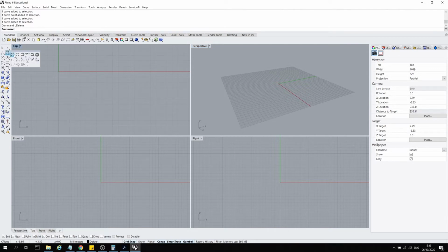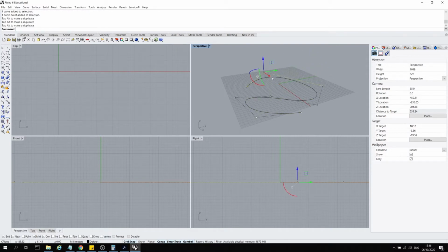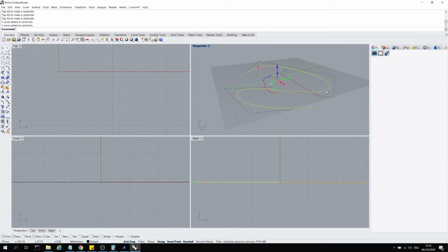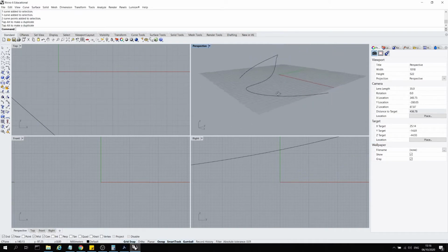We can also draw a curved line. This will allow us to draw perfectly curved lines through control points. By clicking enter, you commit those changes, and you can manipulate them through these points. As mentioned earlier, everything in Rhino is done through mathematical calculations, so we end up with a perfectly curved single geometry rather than a segmented polyline, as we see with other software such as SketchUp. These lines can be moved in any direction as well, like this, if you need.